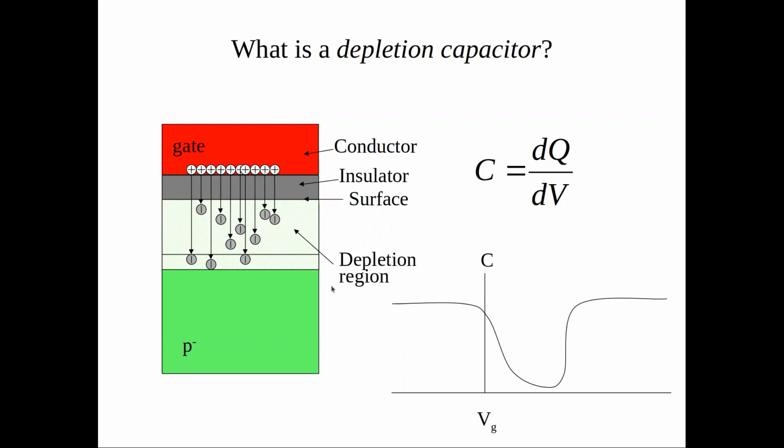But as you push away electrons... sorry, I made a mistake, holes. As you're pushing away holes, you're getting more negative fixed ions. So the charge increases also, because the distance is increasing, but the charge too. The charges are always there. They're there with or without the mobile holes around them, right?